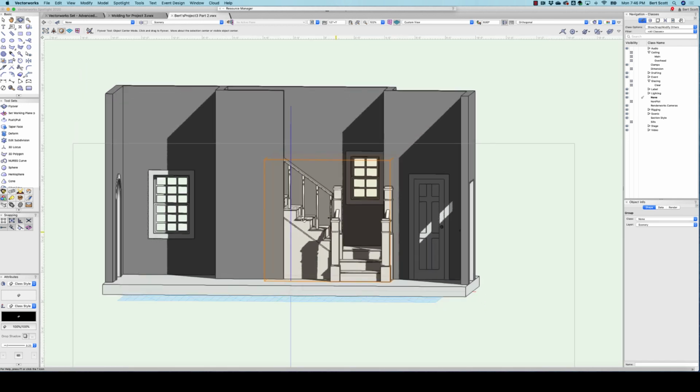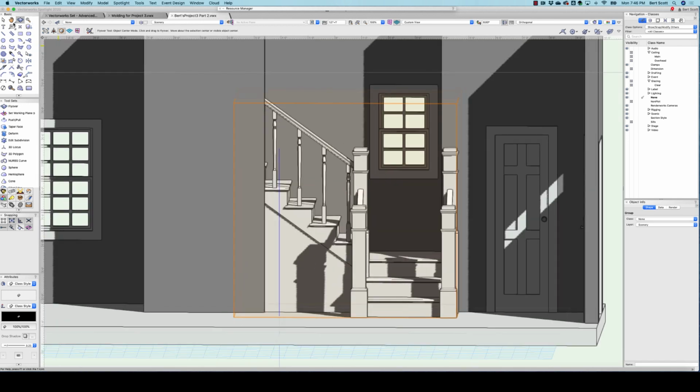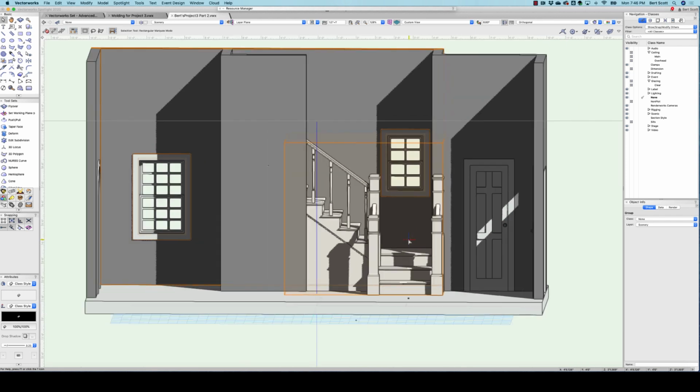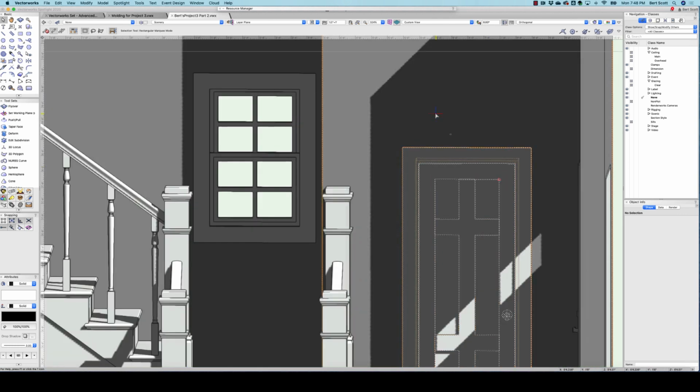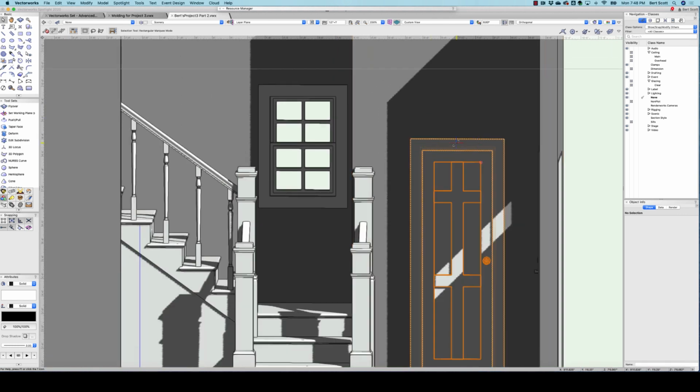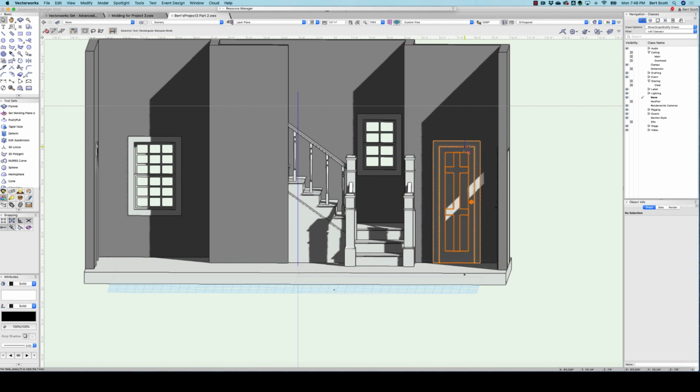So next we'll do some molding, and I promise that the molding is much less tedious than the staircase. The whole rest of the room will not be nearly as labor intensive as the staircase was. The first thing we're going to do is deal with the door and window casing. The built-in Vectorworks door and window tools provide trim, but it's pretty generic. It's basically just a one by. So we're going to replace this generic trim with actual molding.